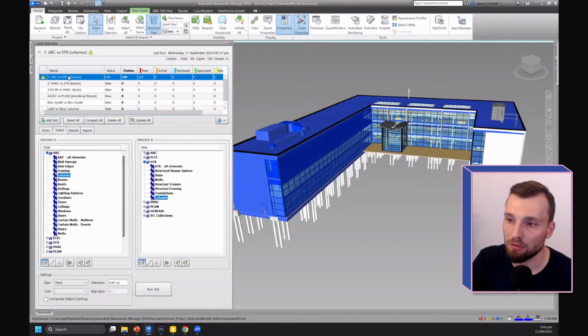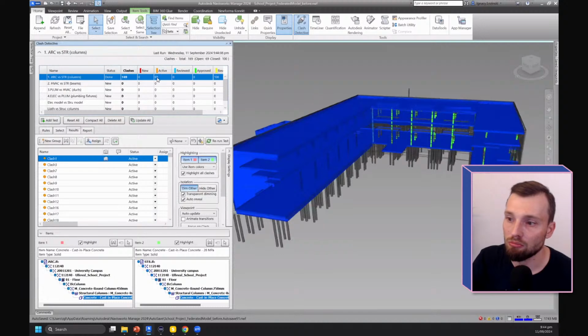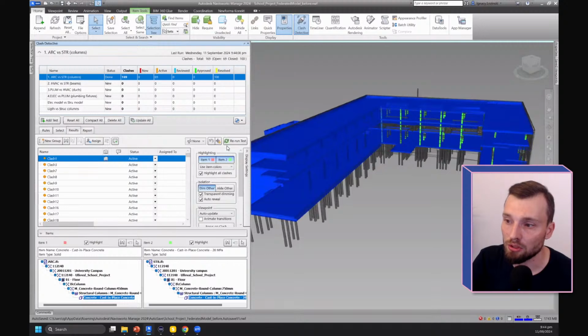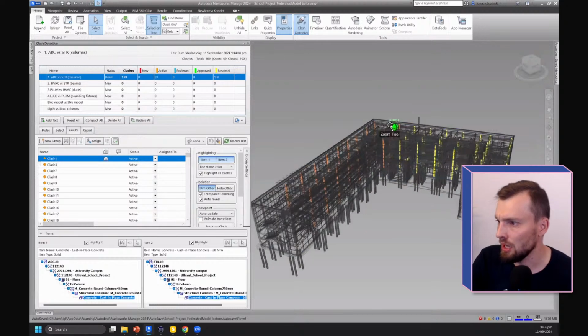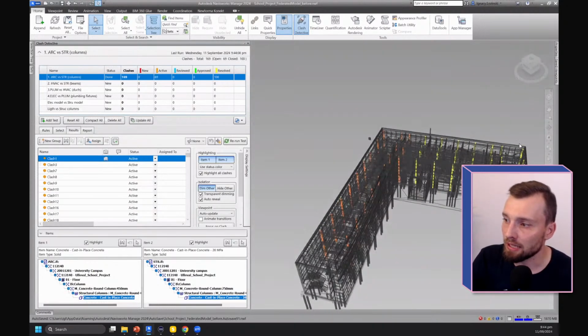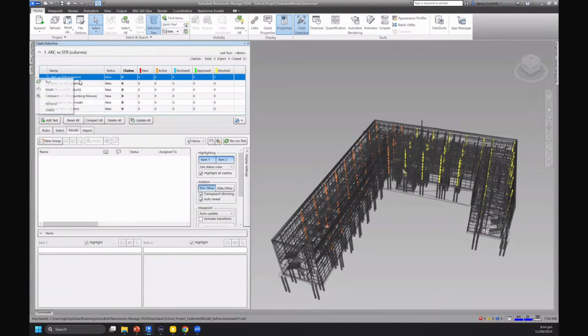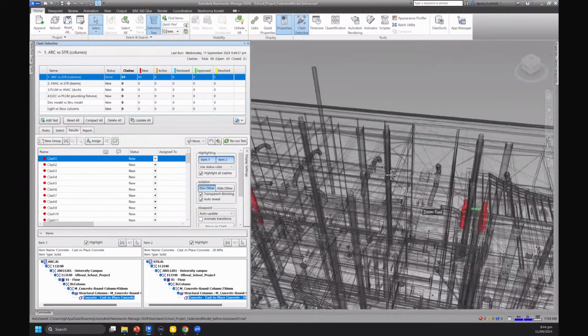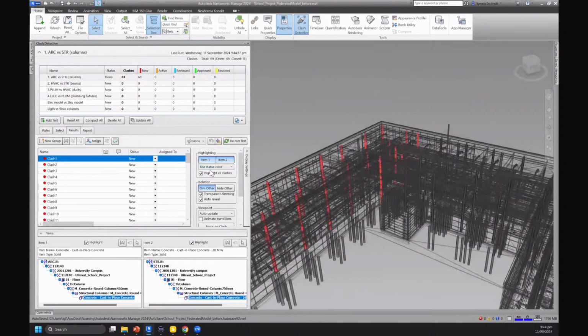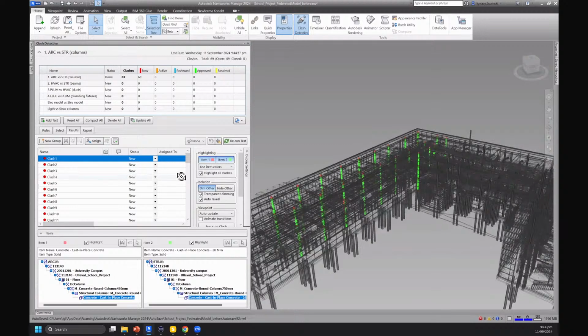So right now, if I rerun the test, you see that active issues are 69 and resolved issues are 100. What does Navisworks mean by that? You see that the orange issues are active, the yellow issues are resolved. It means that Navisworks treats all the issues that were ignored by the rule as resolved. So if I reset this and rerun it, we have these issues in place.